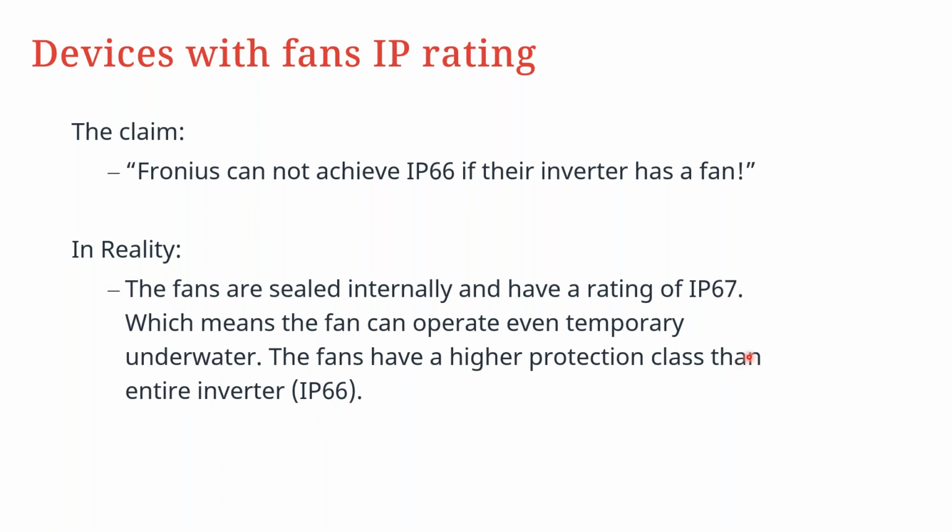As for the construction of the cooling mechanism, as we have mentioned before, the fan is not pushing air inside the inverter. It's just blowing air over the heatsink. Then internally in the inverter, there's another enclosed fan that is circulating the air to prevent the formation of hotspots.